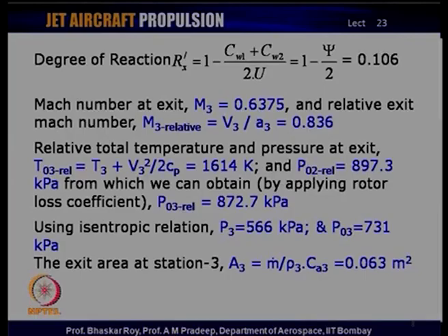I need to mention very clearly here that the rotor loss coefficient that was prescribed should be applied across the rotor on a relative frame. So, the 8% loss that was prescribed should be applied to P02 relative, and if you do that, you get P03 relative as 872.7 kilopascals.